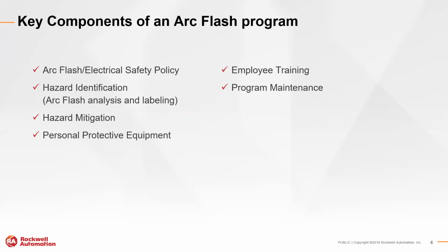Personal protective equipment, or PPE, is more of an obvious component, but once you understand the arc flash risk after you've done an arc flash study, of course, I want to make sure that you have arc flash PPE available for your employees, so they can suit up in proper PPE if they're going to work on electrical equipment. Also, you should ensure that the PPE remains in good condition. You have measures in place to check for the condition of PPE, maybe limits on how many times a pair of gloves could be used, for example, and things of that nature. So the health of your PPE program remains in a good state.